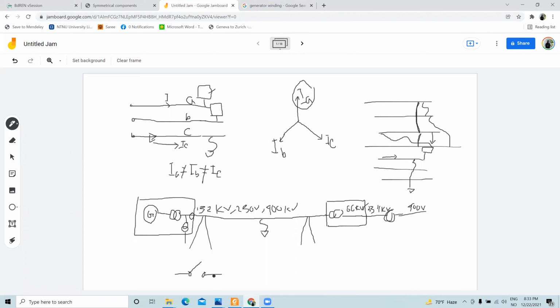Then the two sides of this breaker, one on the left side and the other on the right side, will oscillate with different voltages because of the energy storing elements in the grid. By energy storing elements, I mean the capacitors and the inductors. These are mostly stray capacitors and stray inductors. You cannot see them with your eyes, but they always exist in power networks.